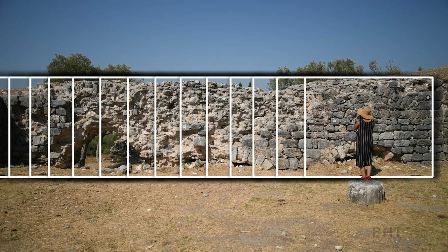Depending on how strongly the object surface is structured in depth, it may be necessary to take the shots not only perpendicular to the wall, but also slightly tilted to the left and to the right. We recommend taking such rotated shots in a separate line. This prevents 2 shots being taken from exactly the same position, which can later lead to problems when aligning the images in the modeling software.